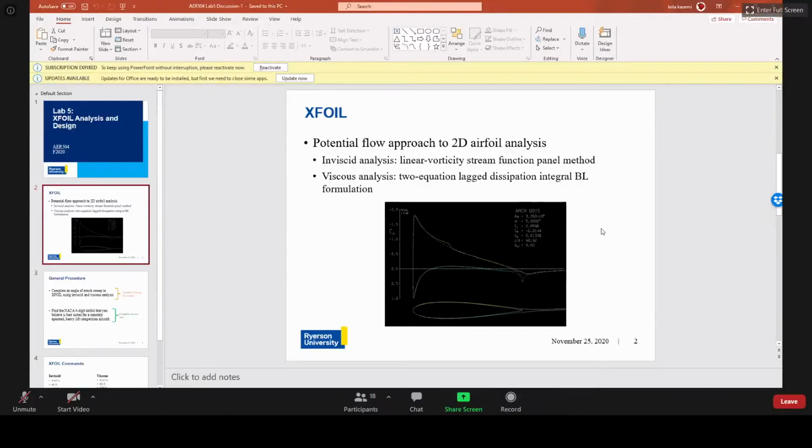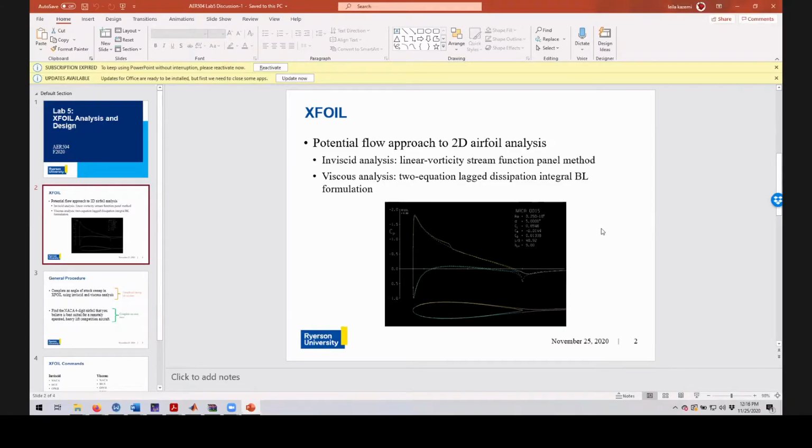Model the surface and calculate the flow. It will give you lift and moment coefficient by direct surface pressure integration, and drag is found from the momentum thickness at the end of the wake. A viscous analysis can be performed by coupling the inviscid solution with a boundary layer solver using a surface transmission model.